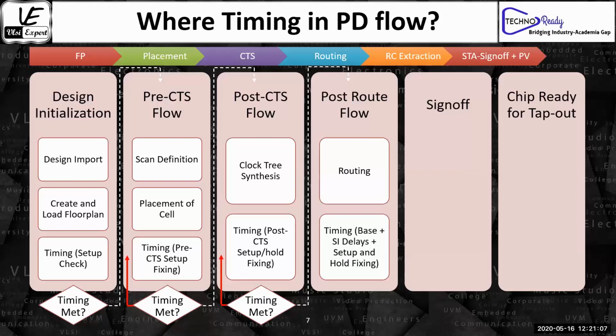When I'm saying timing closure or timing fixing, that means after the placement stage which the tool did, you figure out, okay, there are a couple of violations, and you close them manually. When I'm saying manually, in the sense, you are fixing those things with the help of separate commands, that comes as a part of timing closure or timing fixing. So in one way or another, optimization is something the tool is going to do, but in the backend, the tool is going to do the same thing, fixing the timing by a couple of methods. Timing closure and timing fixing are the same thing: fixing those violations with the help of certain commands or by some methods.